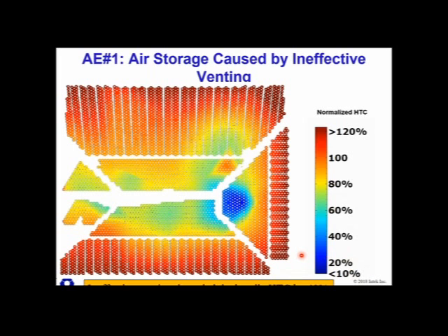I've got one last case study that is a really nice depiction of an airbound zone. This one's another oddball. Here's a bundle. This is the air cooler section in this one, so this is shrouded over here. You can very quickly see that this is an airbound zone out here away from the air cooler.